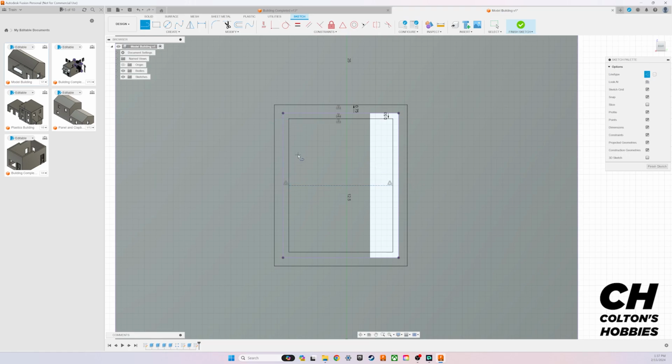And then next, what I want to do is create a centered piece off of this with a rectangle. So centered rectangle. And the reason for this is I'm trying to split the window up and create two different sides. You can see that our current problem is that it's a dotted line. I need to uncheck the construction, and there you go. I have a solid line, so it's going to be a point I can reference, or actually utilize and extrude.